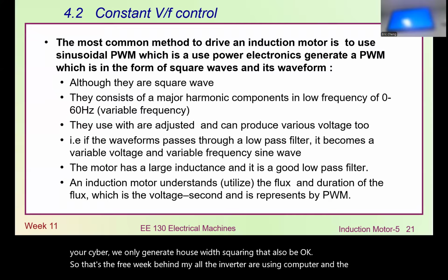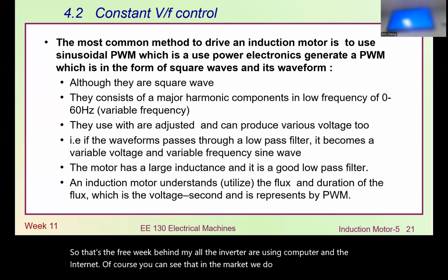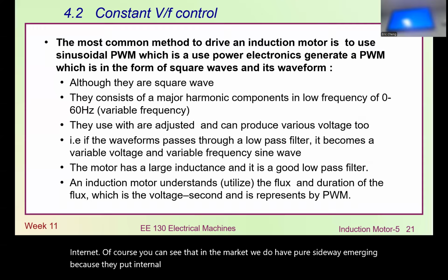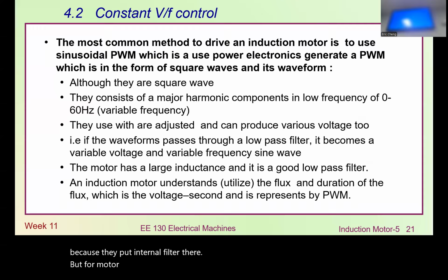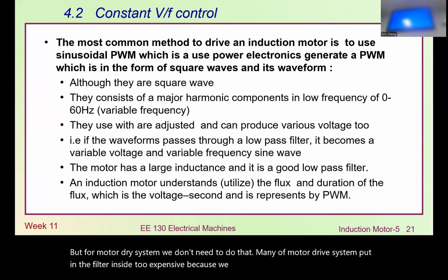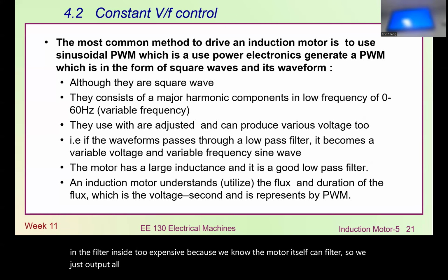Of course, you can see that in the market, we do have pure sine wave inverters because they put an internal filter there. But for motor drive systems, we don't need to do that. For many motor drive systems, putting a filter inside is too expensive because we know the motor itself can filter. So we just output all the square wave or PWM waveform to drive the motor.